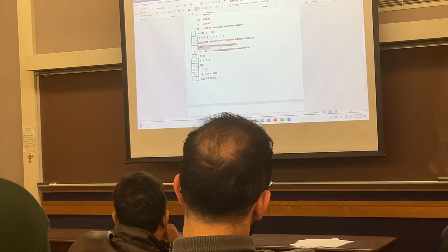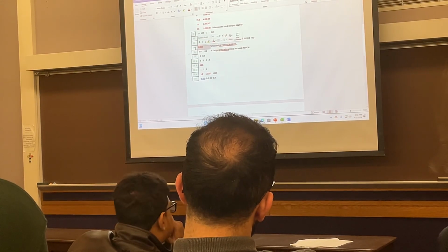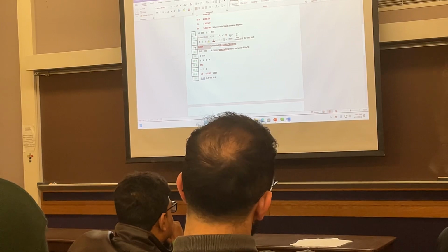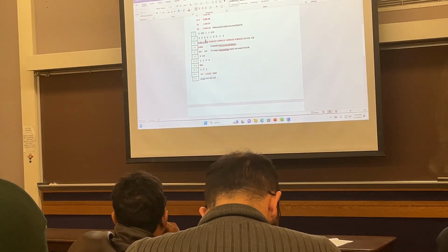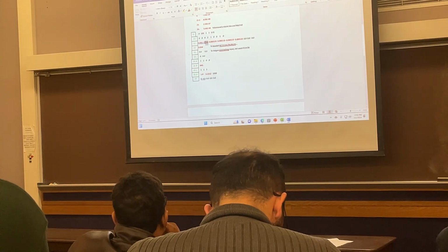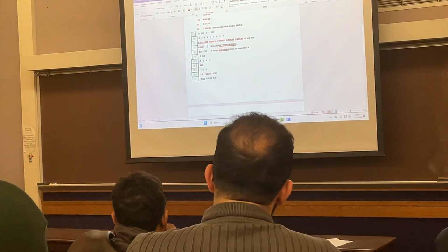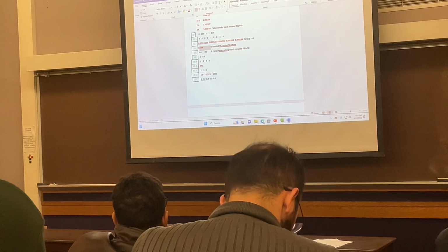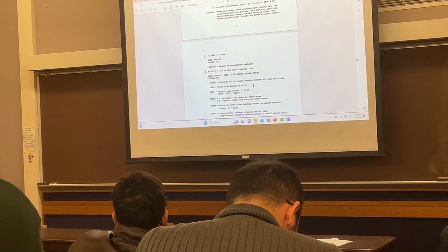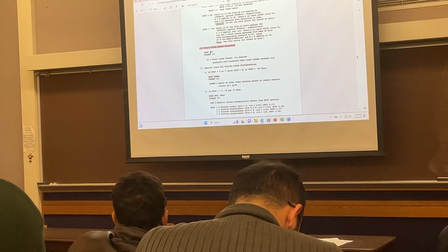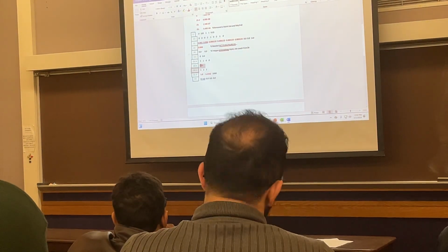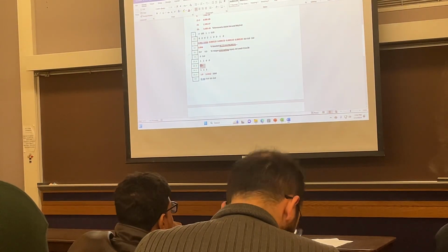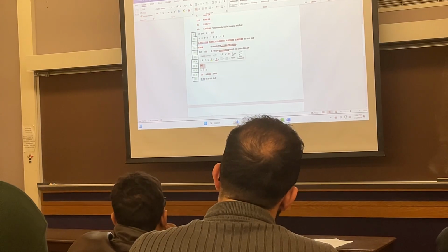This is the final crack length that you define, and usually final crack length is the size of your sample. So for example, here you see the thickness is 4 millimeter, and final length of sample is 4 millimeter. So again, if you go to number 14, final crack length, you just define them. The next one is your stress level that you define, which is 642 megapascal here.